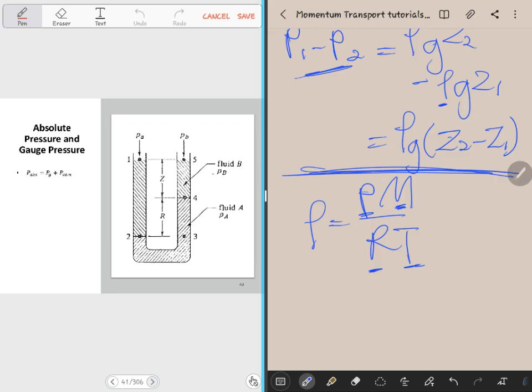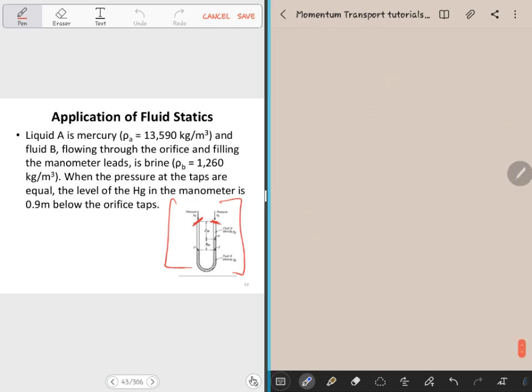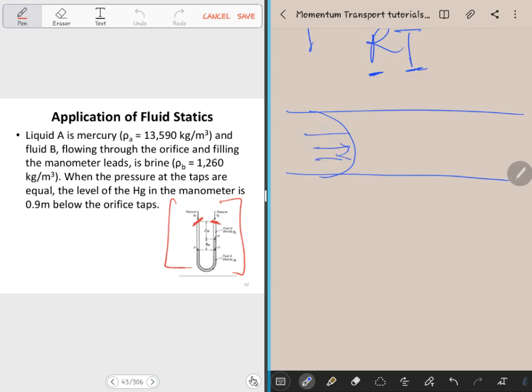So back to the question that we were talking about. We talked about the orifice and now we are done with this particular diagram. Let me redraw it. The manometer is to measure pressure difference. So we have a tube here, let me just attach it already, and the fluid is flowing, having a particular profile. You made this profile later on, but I'm just introducing it here. And then we have an orifice here, and then we place the manometer here.